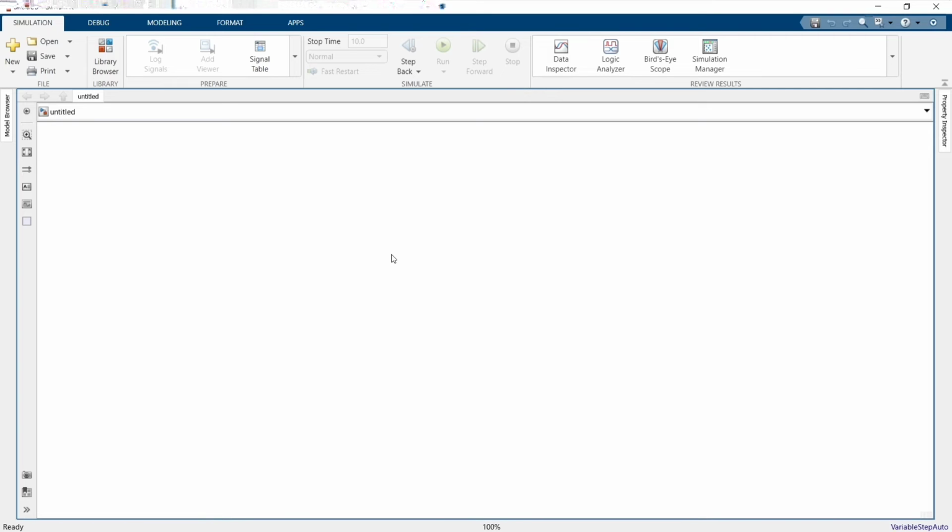So the values that I will be providing in here are 0.65 for my proportional coefficient and 150 for my integral coefficient, and the derivative coefficient will be 2.7E6. I have got these values through calculations. You can also get these values by manually tuning the PID controller. I'll go to saturation. I'll limit the output. The duty cycle limit is from 0 to 1. So I'll limit it from 0 to 0.9. I'll go with OK.